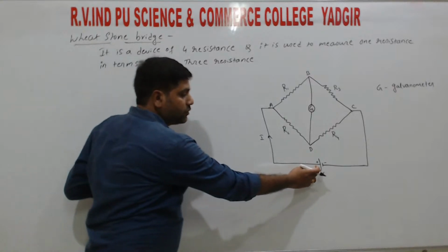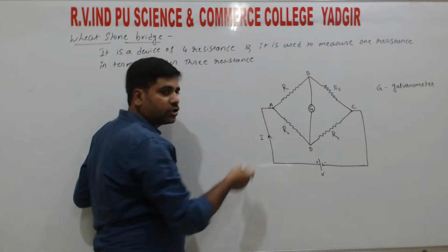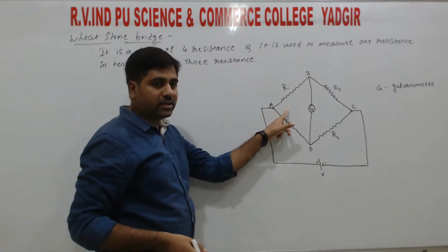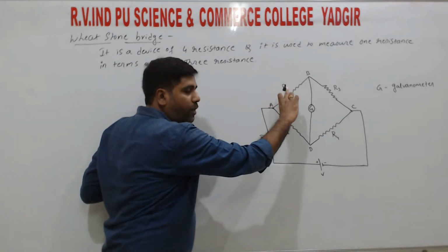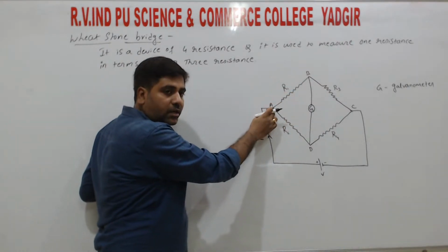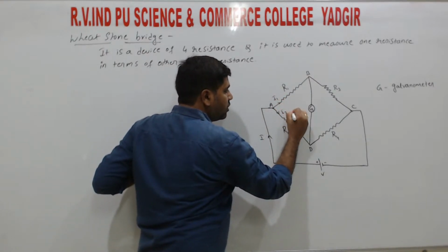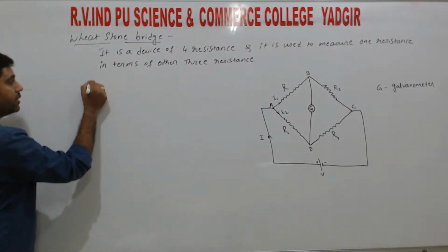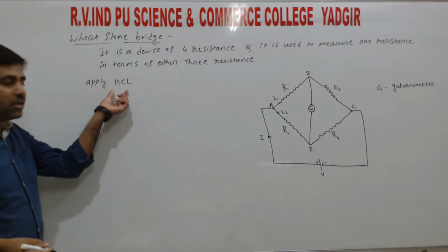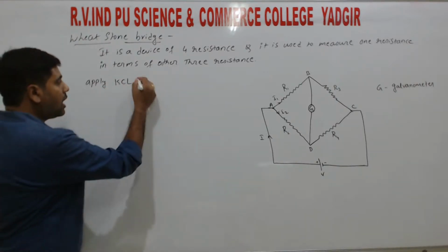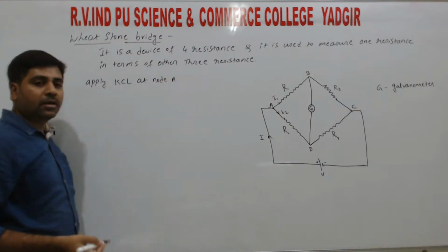Now the current which is flowing from the external source, that is from the battery, at the junction A, from the Kirchhoff current law, the current divides, because here we have only one input current and 2 branches dividing from the junction A, right? So take those currents as I1 and I2. Applying Kirchhoff's current law, in short form KCL, we apply KCL at node A or junction A.